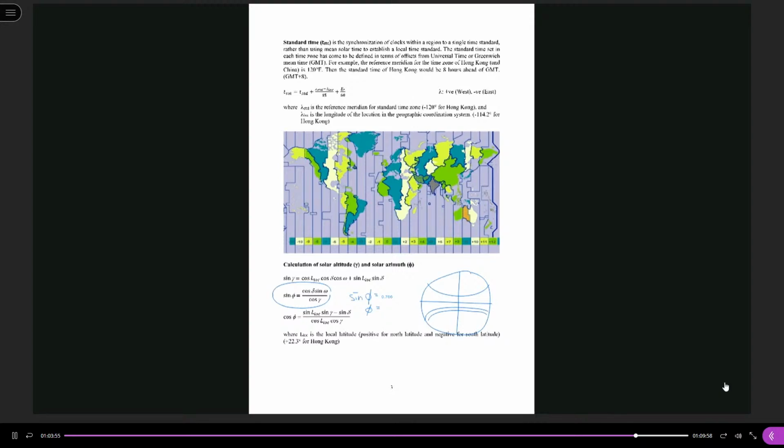But actually, you are trying to calculate the sun position on this day. And for the sun position on this day, what should be the azimuth angle? The azimuth angle should be larger than 90 degrees, right? So for this sun position, the azimuth angle should be 100 something. So the answer 50 doesn't make sense.